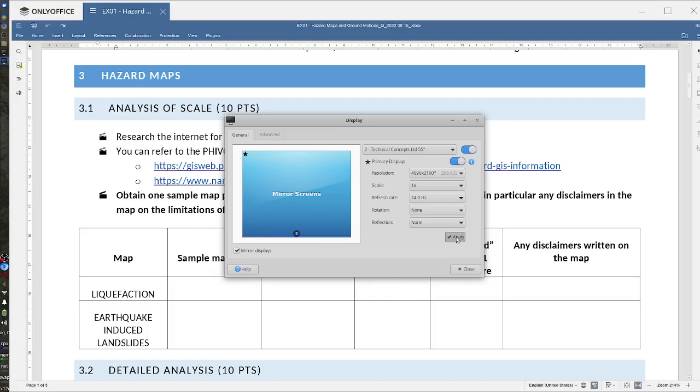Pero sa ganun, sir, parang may soil geotechnical mitigation. Yeah, you can alter that one. What they do is you can mix some cement, or you can densify. You mix some cement, or you can also pound the ground with boulders.